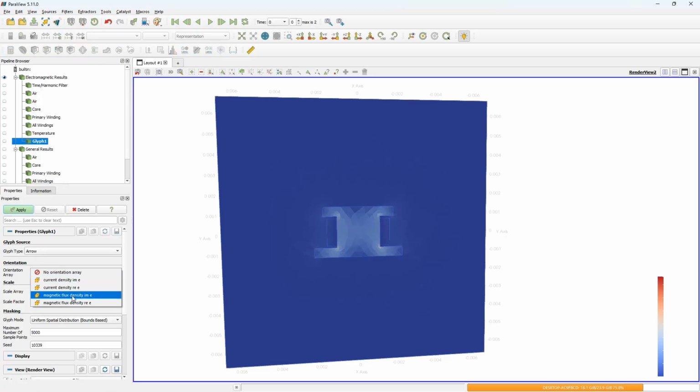And notice that magnetic flux, vectorial magnetic flux, has imaginary and real parts. So you will need to check which has the largest magnitude, which mostly defines the direction of the magnetic flux. And this imaginary and real part, the largest amplitude will depend on the phase that you apply for your coils. So let's assume that in this case it is the real part that mostly defines the magnetic field phase.